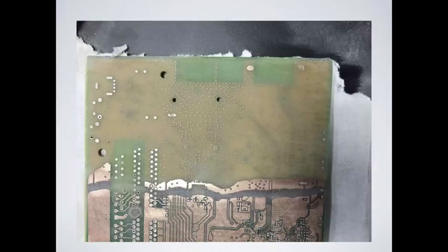But I find that at the very, very least, I would recommend some sanding paper and these guys. So I started off with the sanding disc. This is good. Take off the top part. Start with either 120 or 240. Don't go any lower than that, because it just eats everything up. And then use this guy, the abrasive buff, and then sand it down a bit, and then finish it up with this guy, the detail brush.